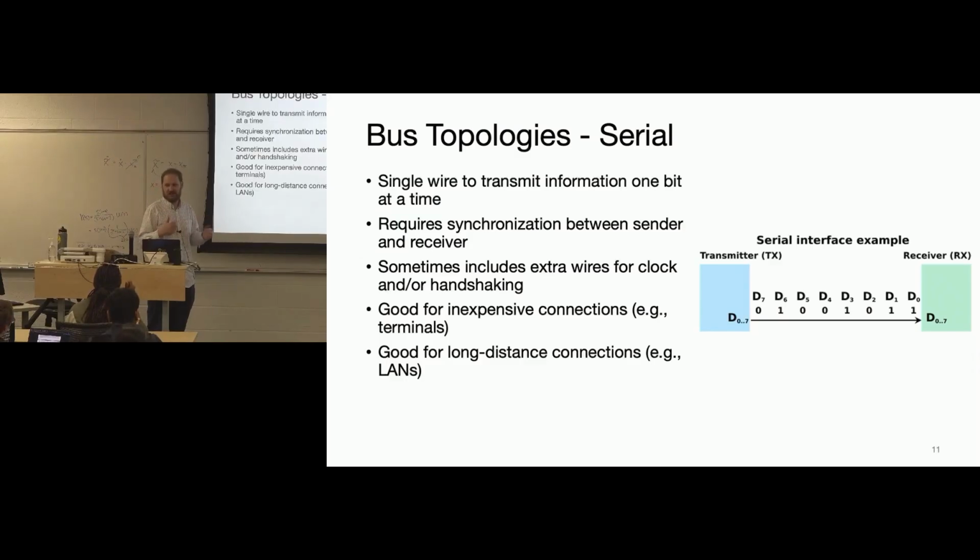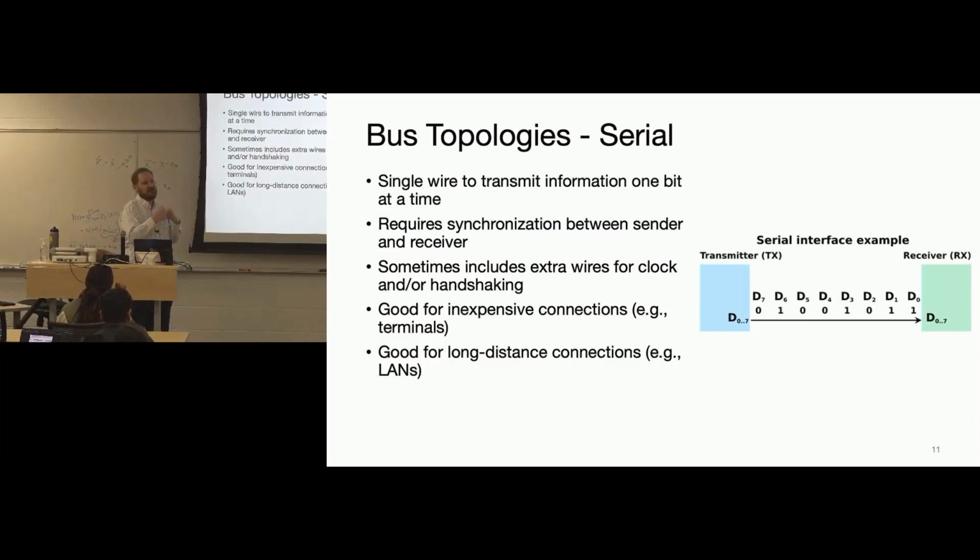So we're going to cost optimize that down to as few wires as possible. Noise and interference is a big one. If you have multiple wires, they're going to interfere with each other because you're going to have different data on them, and you have this thing called crosstalk, which is painful, and you have to do lots of signal integrity engineering by coating each wire with metal or shielding so they don't talk to each other, which is expensive.